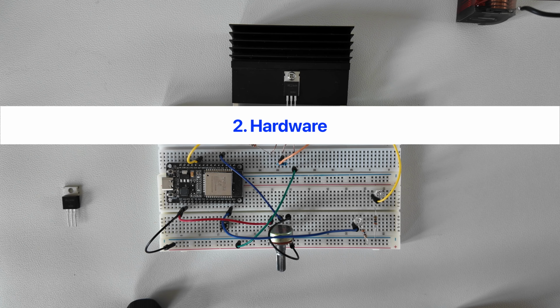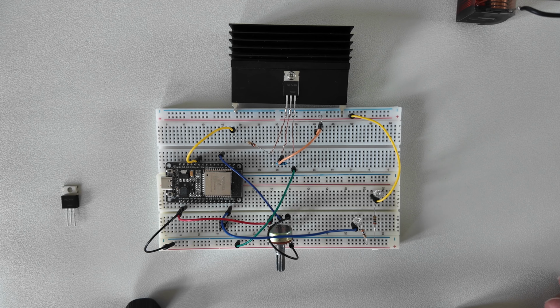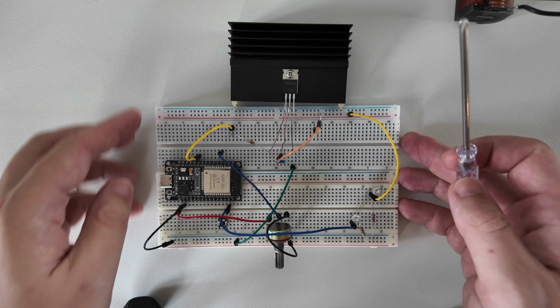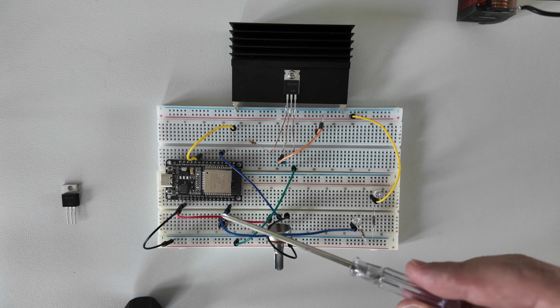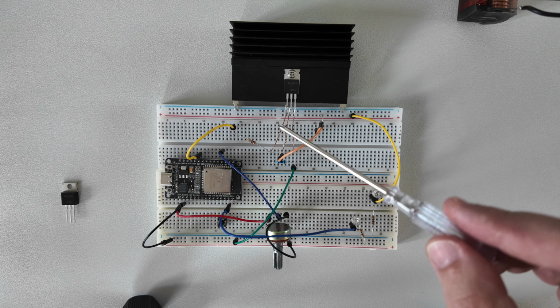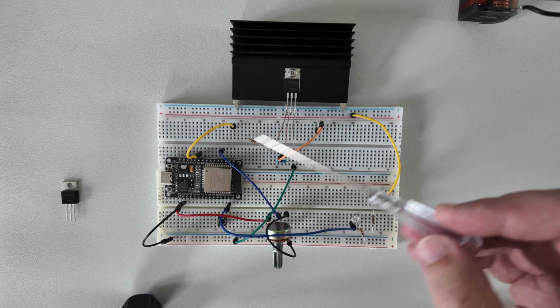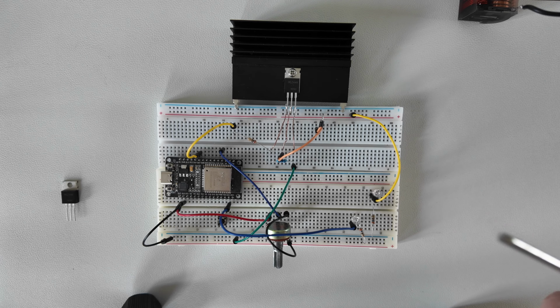As we can see, I am using a breadboard, so we don't need too much soldering. I just soldered several small wires to keep things together, and let's see what we have here. This is obviously the ESP32, and it will be the brain of our system. It will generate the signal that will go to the transistor, because the ESP32 pin cannot handle the high current, so we need a special transistor for that.